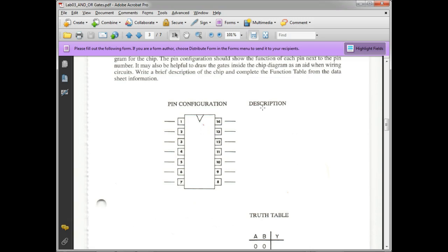The pin out shows you this is a 14 pin DIP. What could that be? Well, that could be NAND gates, that could be OR gates, that could be inverters. So we've got tons of guys that use this 14 pin DIP. It could be a voltage regulator. It could be an adder. It could be a subtractor. It could be almost anything unless I know the pin out. If I don't know the pin out, I don't know how to connect this thing.